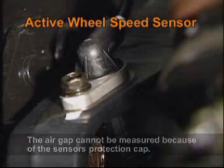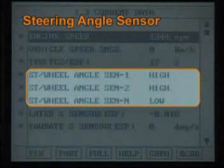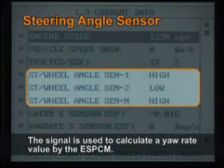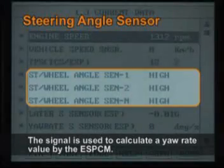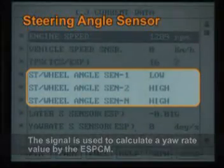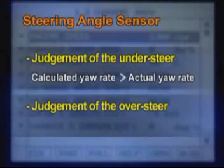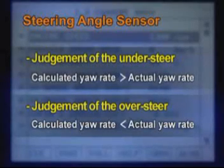The ESP control module calculates the vehicle yaw rate based on the steering angle sensor signal and other inputs while turning. The calculated yaw rate and the actual yaw rate from the sensor cluster are compared together. The difference between the two values is the basic factor to determine the vehicle's understeer or oversteer condition.